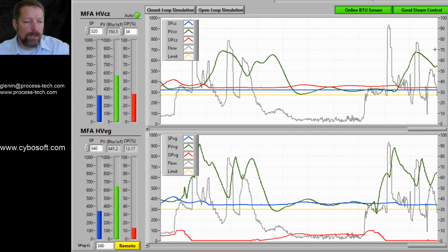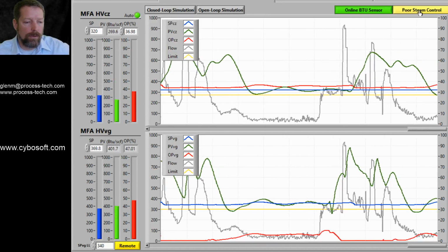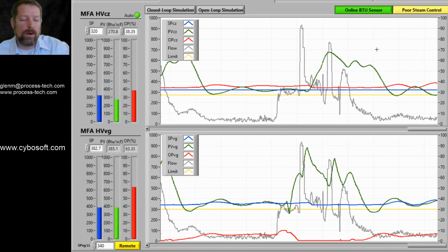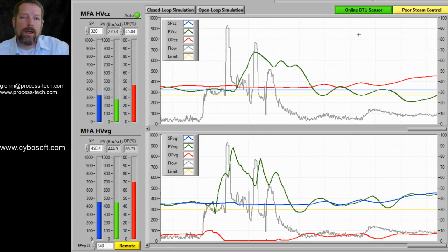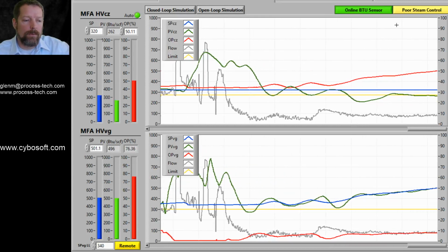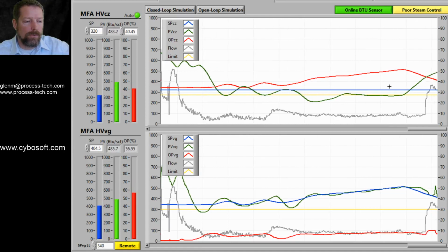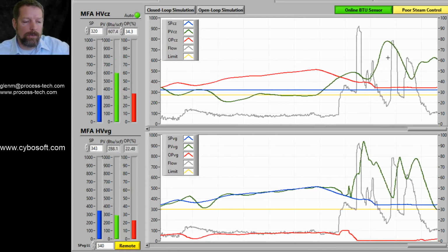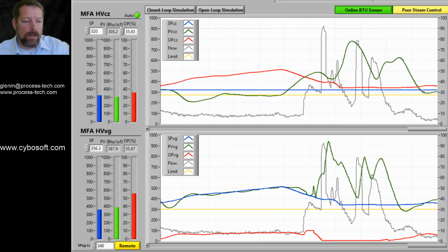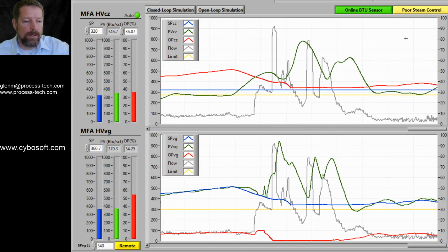If you don't have sufficient steam control, and again this example is assuming the customer has steam, we are aware that many of our customers have air assist, and we can talk about that in detail at the training class in April 3rd. But if you have poor steam control, you can see how the steam control would challenge the control system to achieve set point. Again, the goal of the operation here is to stay above the yellow line.